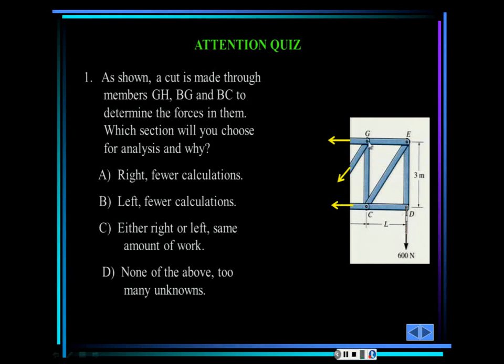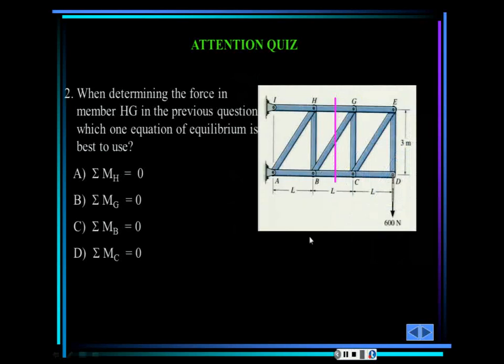And I can start doing summation of moments here, calculate this, and then summation of moments here at the concurrent point, which is the joint between these two, and I calculate this one. And summation of forces in Y to calculate the next one.